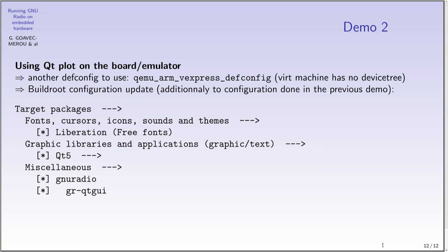The device tree is a description of the hardware. It provides the CPU type, the peripherals available or not, controllers and peripherals. So it describes really the configuration of the board instead of a big file. It's a current, modern, and stable way to have this description.